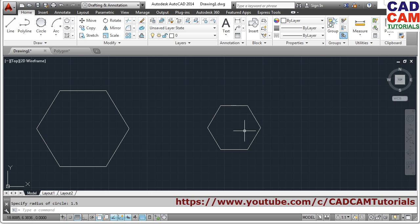Again, this distance of 1.5 will be from the center of the polygon to the midpoint of any of the lines. If we just try it, measure distance, then track these two points, click, that is, this is 1.5 distance, and that means the face to face distance will be double, that is 3.